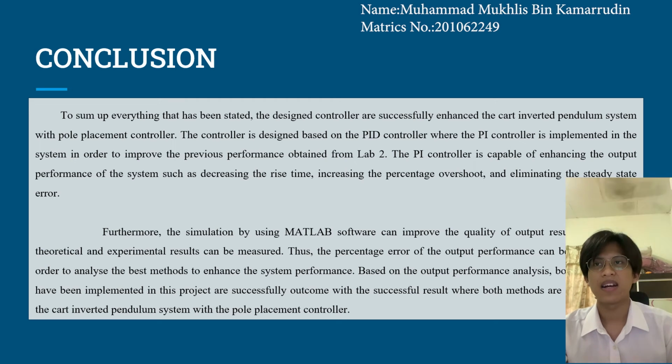Today I would like to sum up everything that has been stated. In the design, the original cart inverted pendulum has a substantially high magnitude of steady state error. The error was eliminated through the implementation of the proportional integral, which is the PI controller, with the Ziegler-Nichols tuning method. Even if the mathematical modeling is unknown, it is possible to balance it by evaluating the response of the system and tuning each gain until a positive result is achieved.